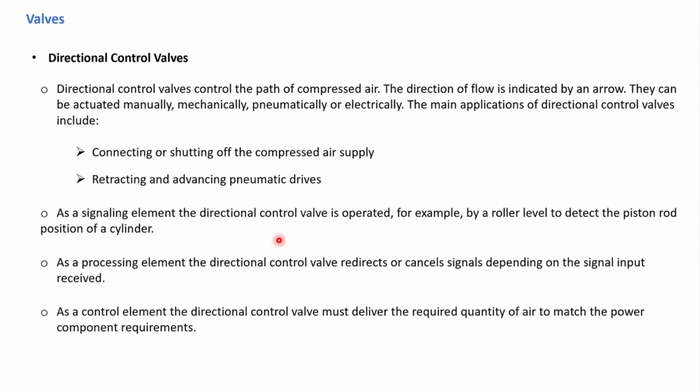In that pneumatic circuit we can have a directional control valve which is connecting a manifold to a twin pressure valve, for example. And from that twin pressure valve we have the connection to a pneumatic actuation for another directional control valve, and this directional control valve is connected to the actuator. So the first one can shut off the air supply for the twin pressure valve, and the second directional control valve can shut off the air path towards the actuator.